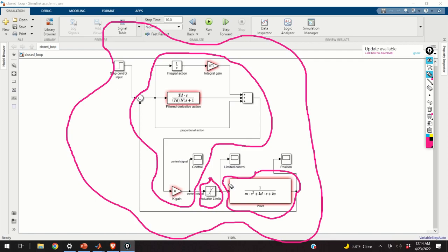Actuator limits are a very important part of our model since they will enable us to simulate more or less realistic actuators, because every actuator cannot exert an infinite amount of force or torque. Consequently, we need to limit the amplitudes of exerted forces and torques in our model.